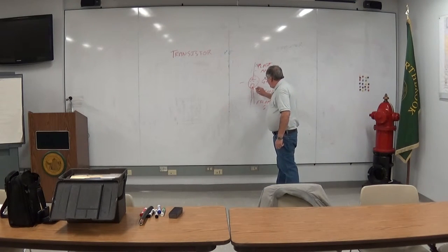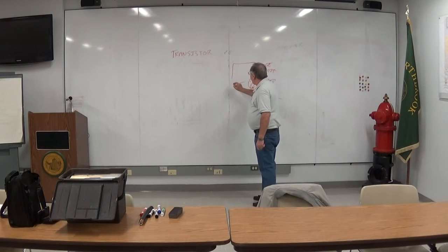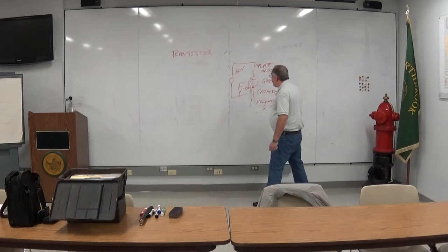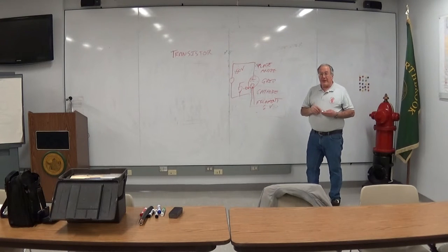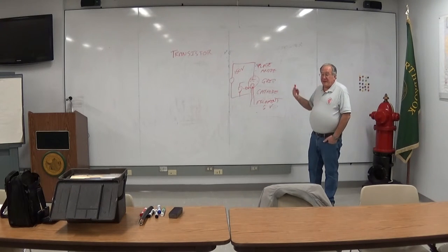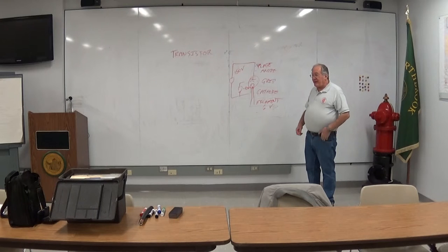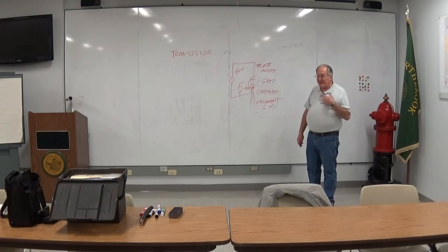That would heat up the cathode, and between the cathode and the anode would be a high voltage thing, about 150 volts or more, and then the grid would be fed with some other, typically turned in negative direction, about 100 volts or something like that. You'd have to have a battery pack that had all of those voltages in it to make a vacuum tube work, and then you had a number of vacuum tubes in the radio, so it was a big thing.